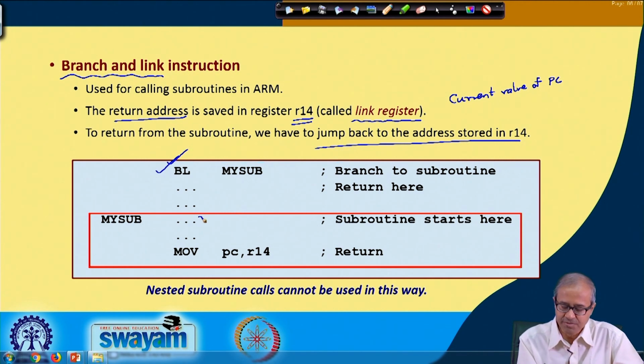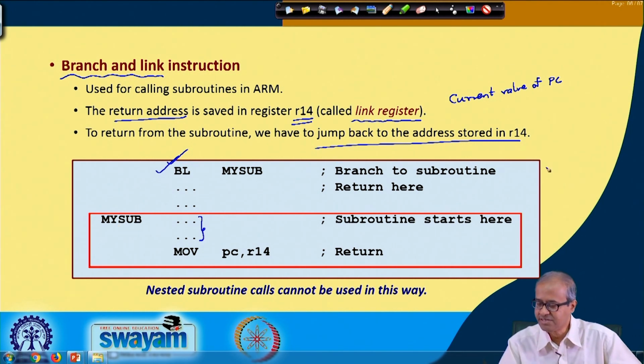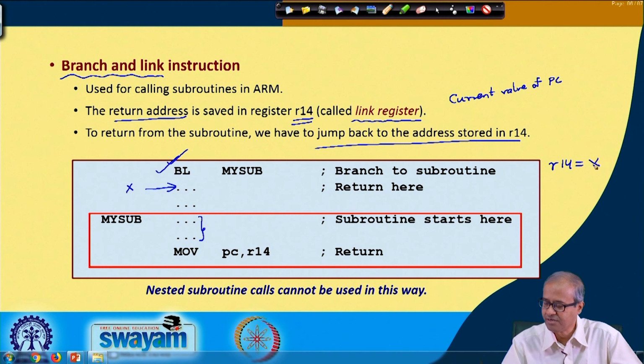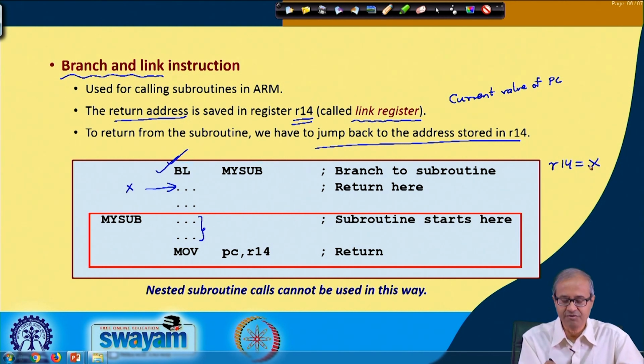Inside this subroutine there will be some instructions, but before jumping to the subroutine, what will happen? In this link register, R14, the next instruction address, let us say this is x, will get stored. The current value of the program counter, x, will get stored in R14, and then it will branch to my sub. In my sub it will execute several instructions. At the end, when it wants to return, it executes a move instruction: move R14 to PC.